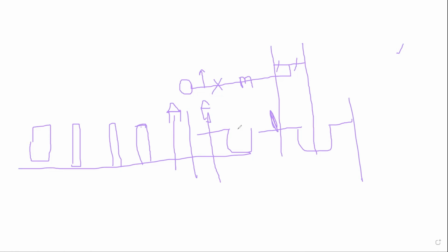We cannot go like this because all these phases are at the same level. So I have to arrange one more level of conductor on the top, and I have to connect this one to this, and I will drop here. Again, I will drop here and connect to this as well as this. So depending upon the layout connectivity, in some cases we require this kind of bus, which is not a bus in the SLD. It's for connectivity. I am making a bus, so that bus we will call a jack bus.